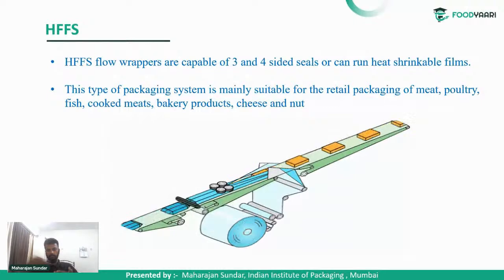Below the sweet boxes, there is an unwinding layer which unwinds the packaging material, and it folds into a cover. And then firstly the fin seals are made, then the end seals, the bottom end seals, are made. Then while sealing the bottom of one end, it also seals the top of the other end, and also cuts it, and detaches it from the line.